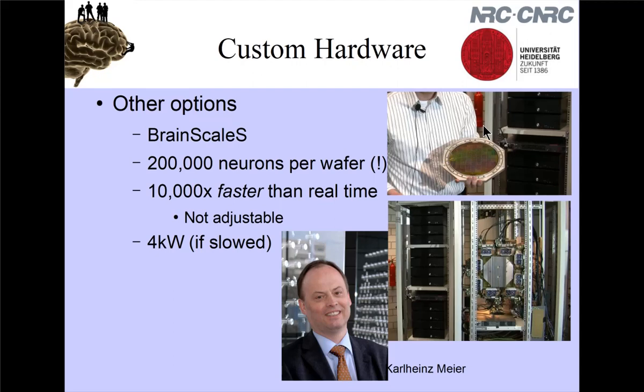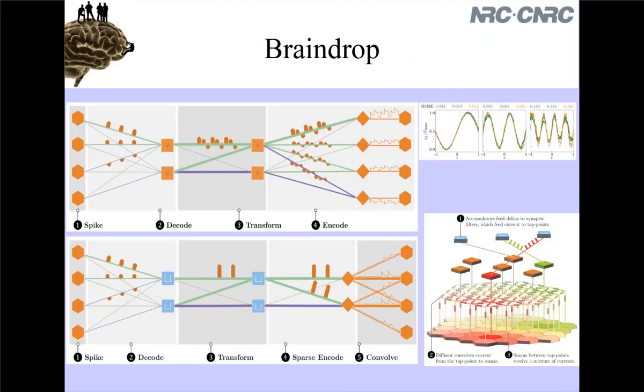And they decided, hey, a lot of the applications of neurons are things like learning, and that takes a while. So instead of designing the dynamics to be close to real time, so for instance, with the Braindrop chip that we made, if a spike happens, the effect it has on the next neuron is suddenly large, and then it slowly decays back down. The thing that in biology would be the release of neurotransmitter and then decay back down. There's a time scale of that delay, right? And in biology, it's somewhere between 2 milliseconds and 200 milliseconds. And so that's what Braindrop targeted to make sure it would have the same time scale.